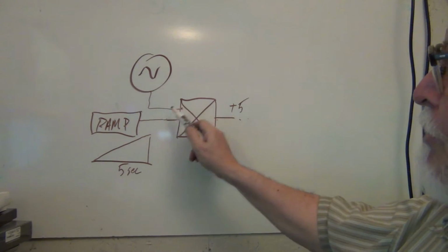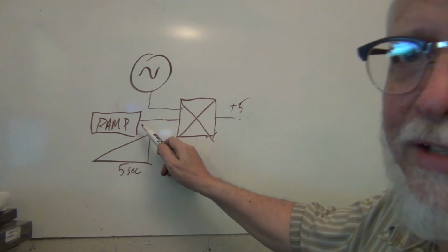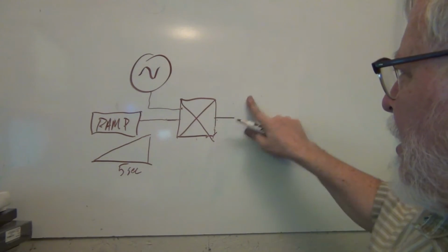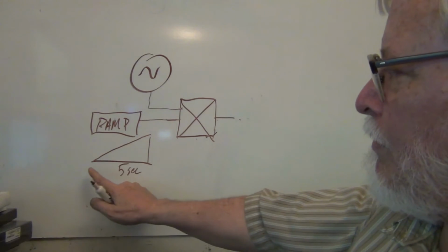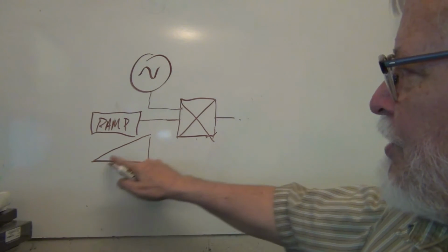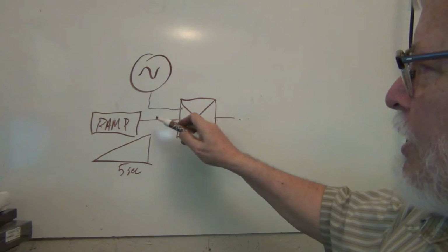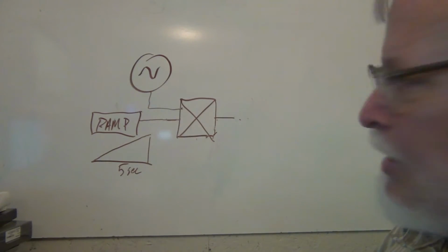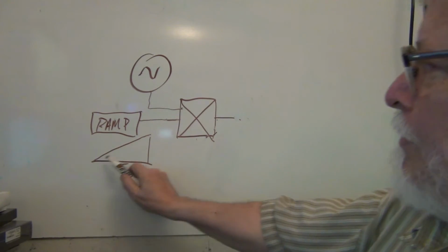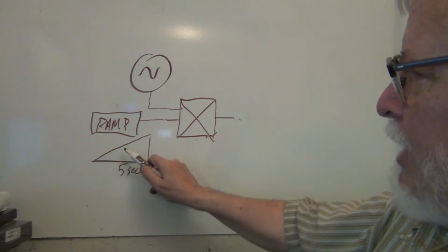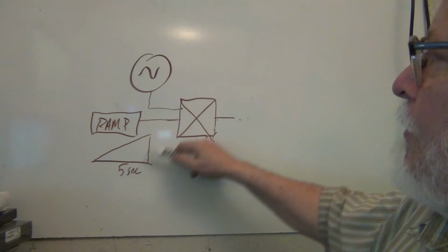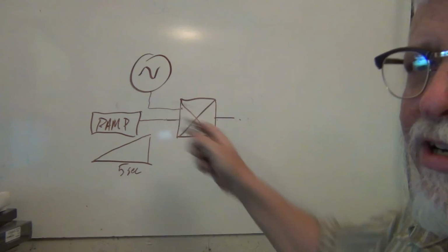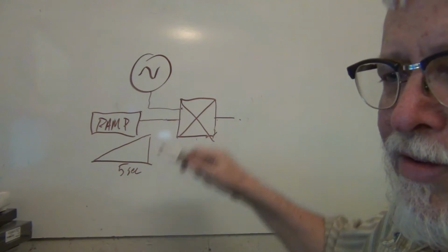All right. So what's going to happen is when this ramp is at 0, when it's reset, anything times 0 is still 0. So you get nothing out of here. You turn the ramp loose and it goes from 0 to 10 volts. And what's going to happen is that the amplitude of this oscillator is going to get turned on by this function. So it's going to start like that. It's going to go to maybe plus and minus 5. Then it'll go to plus and minus 10. So the multiplier is used to turn on and off another analog signal with a voltage.